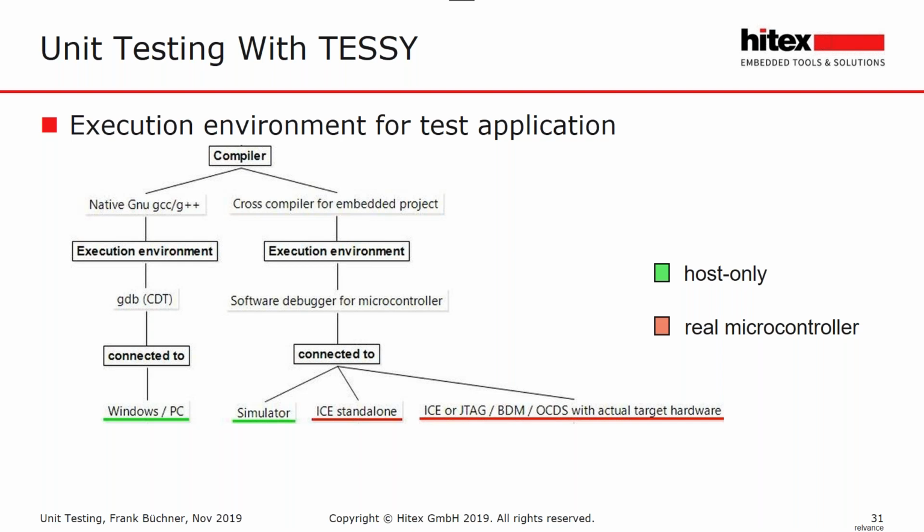And usually, the debugger software which you use in your development environment is this execution environment. And this execution environment can act as an instruction set simulator, or it can be the interface to, let's say, a JTAG debugger, BDM debugger, or a circuit emulator, or something like that. This is not important for Tessy.